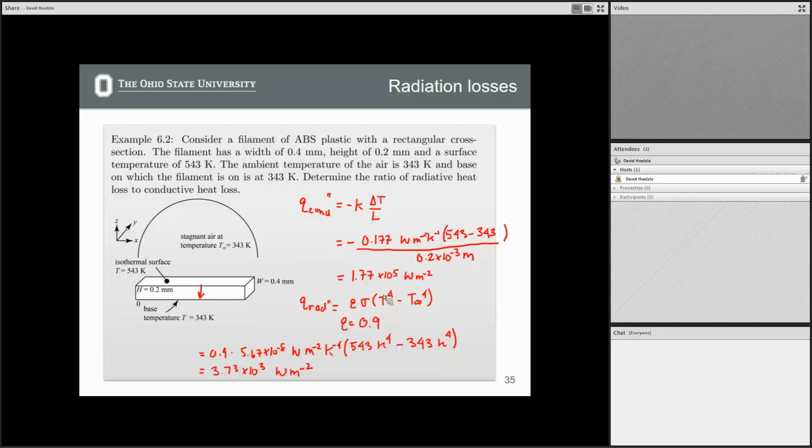So for the life of me, I cannot find the change in surface tension with respect to temperature for polymers, to see if there's any type of Marangoni convection. No one reports it as far as I can tell. People who model material extrusion never talk about Marangoni convection. So I think it's pretty safe to say it doesn't really happen. Polymer melts have a considerably higher viscosity.